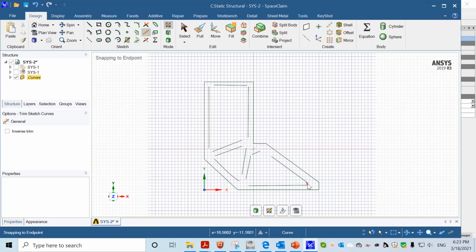We'll trim away all these corners, and then we'll use the round corner function to generate a corner for it, where you can use a value that you want to set up. Here I will use 2 to be consistent. Whenever I am able to use 2, I will use 2.